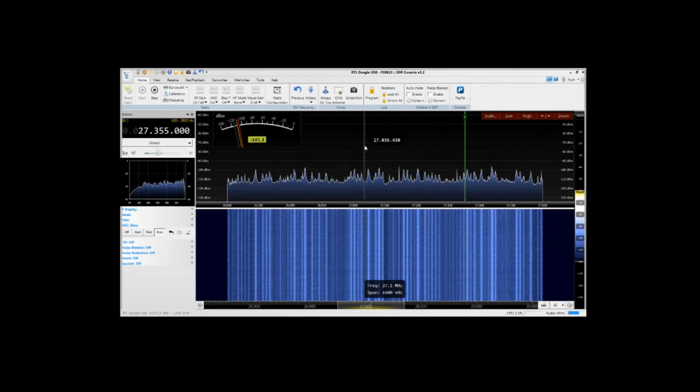So we'll close that, and yeah, the volume there. And what I like about Console is it actually has squelch for AM and SSB, because you can set the point where you want the squelch to be, and then if a signal comes through on skip or something and it's a reasonable level, it will open up this squelch, and you'll hear it at the preset volume level.